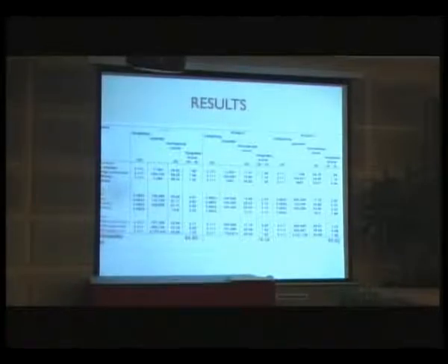But if you include the cost of maintenance, you find that bridge 2 is only 10% cheaper. These numbers are based on a certain traffic flow rate, and if you did some kind of sensitivity analysis, you may find that the figures aren't that far apart, in which case bridge 1 might be a better option, because given its sensitive location, that's going to be a more pleasing structure for this particular location.